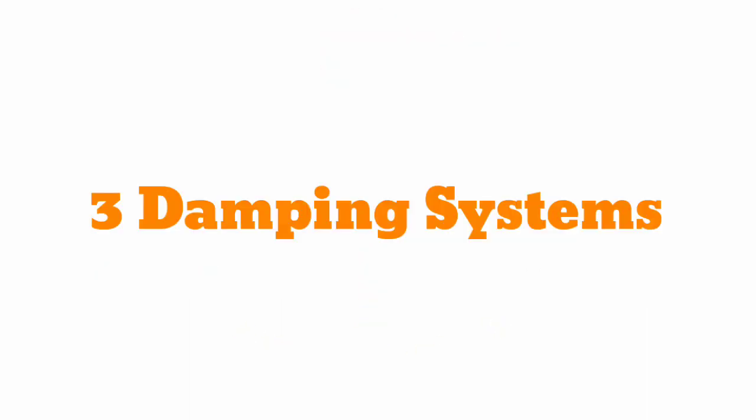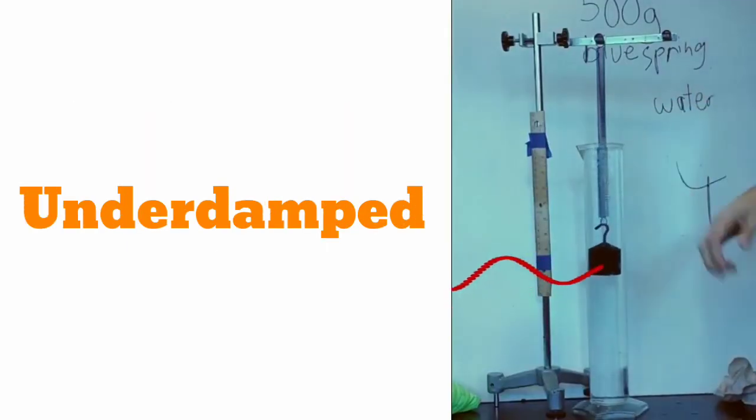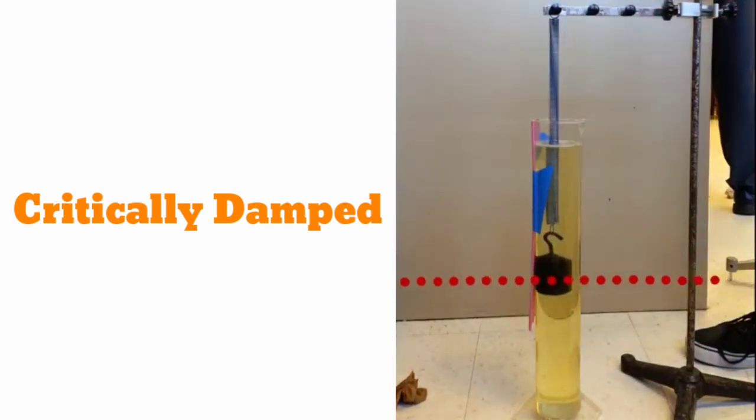There are three types of damping systems: the underdamped, critically damped, and overdamped. If the instrument is underdamped, the moving system will oscillate about the final steady position with a decreasing amplitude and will take some time before it comes to rest. But when the moving system moves rapidly but smoothly to its final steady position, the instrument is said to be critically damped or deadbeat.